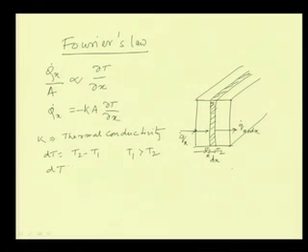dT becomes negative. But we know that Q dot X is in the positive x direction, and that is positive. So, to make the heat transfer rate Q dot X positive along the x direction, another negative sign is added to this.